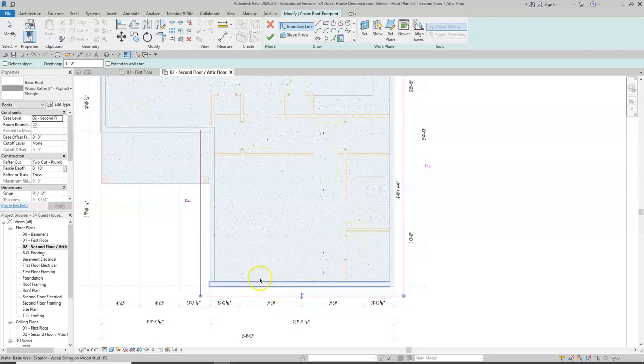All right, moving forward. Also note that we have an overhang here, so the roof extends outside the wall. We had our Pick Walls button selected, and I just selected out of habit, and it immediately offset 1 foot outside the building. That is exactly correct. So our overhang will be 1 foot. That is the default.